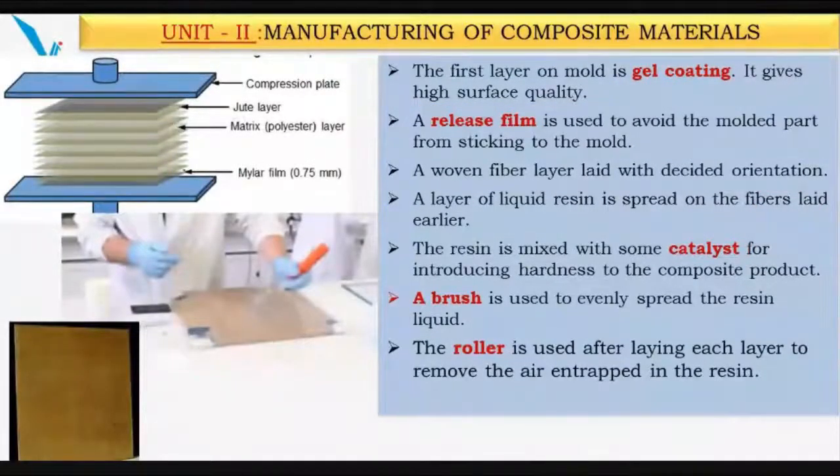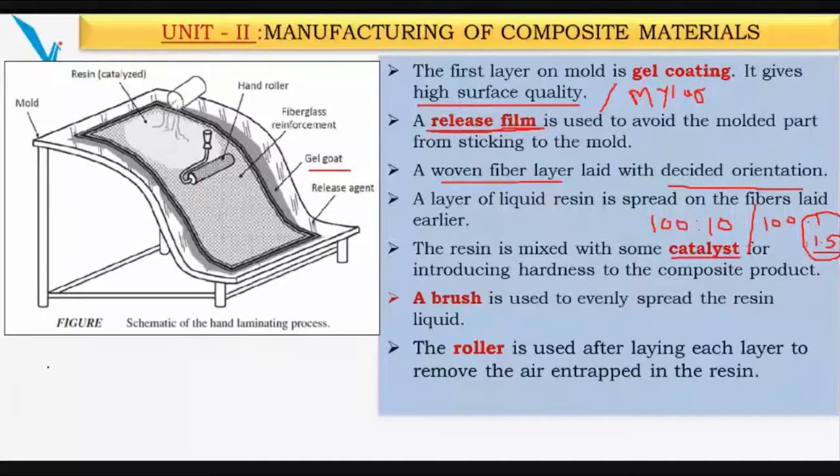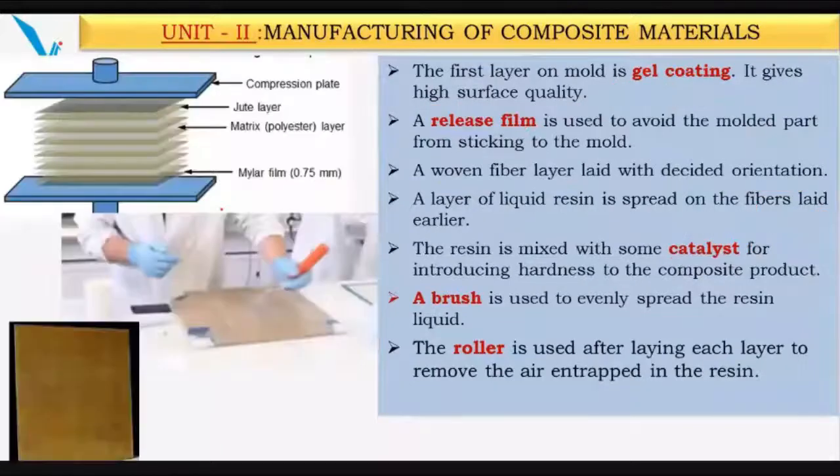Again, this method is a layup process supported by compression molding, because for some particular fabrics, if you just apply the resin and keep it, then after some time the layers will come out and bulging will form. So you need to compress this. Generally this happens with jute fiber, as I have experienced.